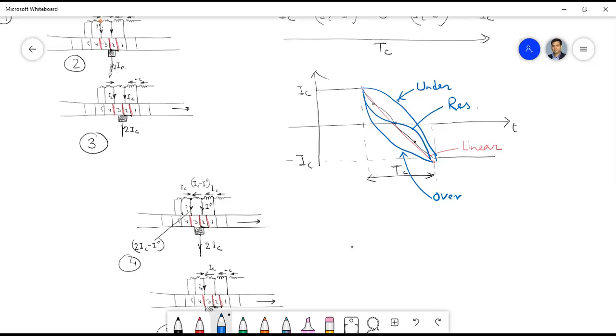Due to the speed EMF also, there can be some EMF during the commutation. Though the commutation must occur where no EMF is induced. You should remember this point. Therefore we place the brush in such a location where no voltages are induced, but it cannot be avoided always. Sometimes there is some voltage induced in the coil in the commutation region as well.